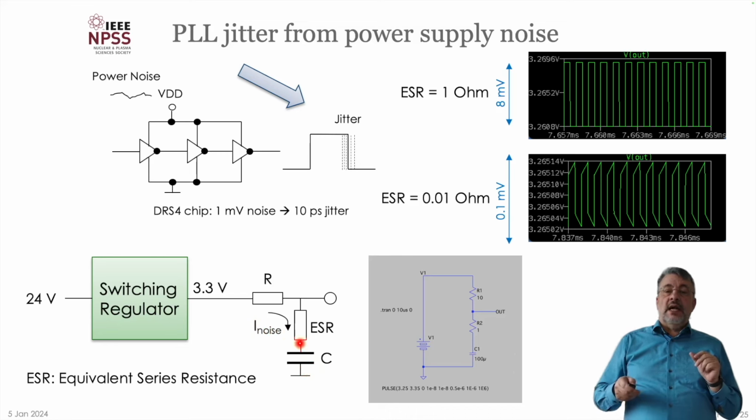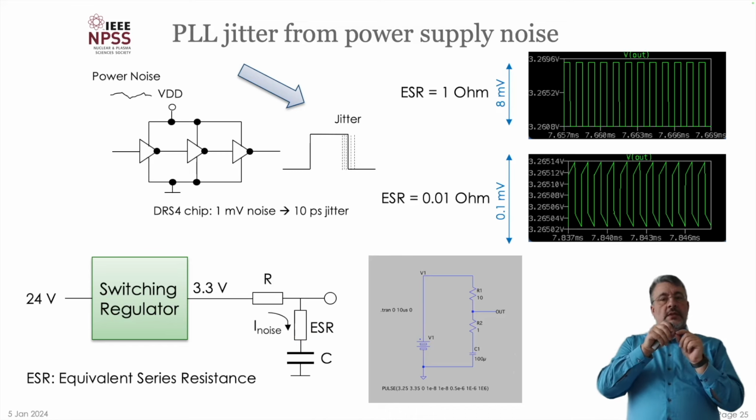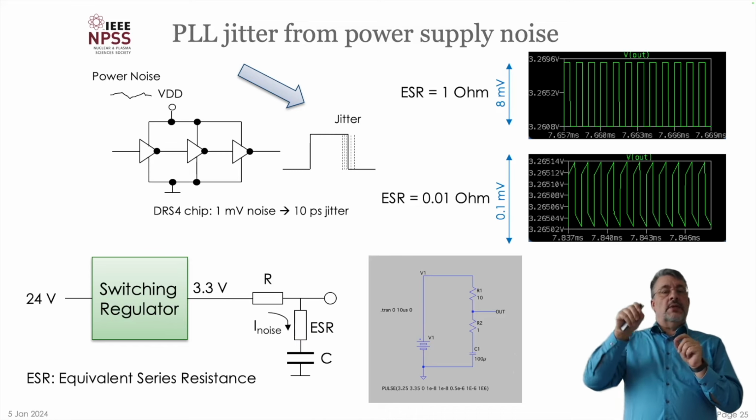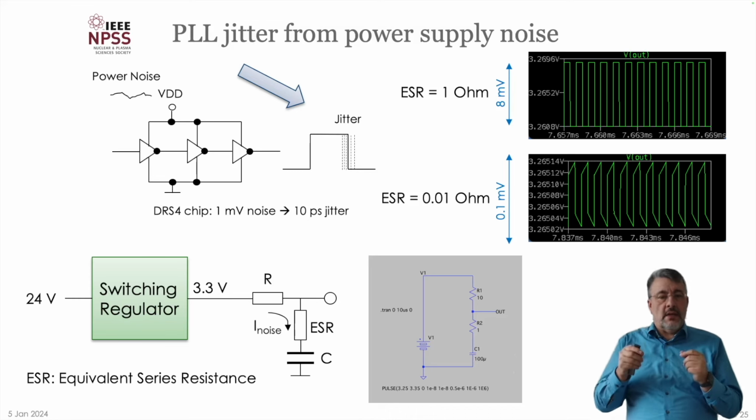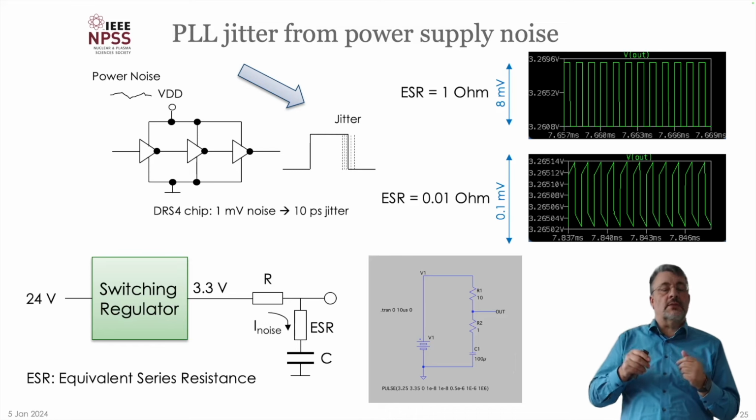capacitor here has what is called an equivalent series resistor, ESR. And this is typically in the order of like 1 or 2 ohms, and can be just the leads leading into the capacitor, or the internal metal inside the capacitor, which has some resistance which is not zero.